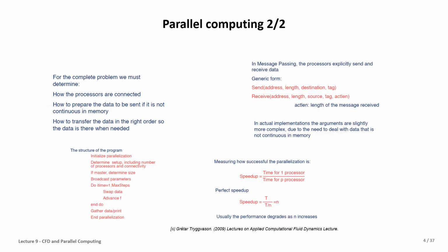Just to remind you, in the OpenFOAM introduction, lectures 4.2 and 4.3, we used the Rescale cloud computing. With the examples presented in those lectures, we used this capability to decompose the domain of the problem. The example we had in OpenFOAM was 2D, and the example of the Rescale cloud computing was 3D, and decomposition is used to divide the domain into subdomains between a number of processors.